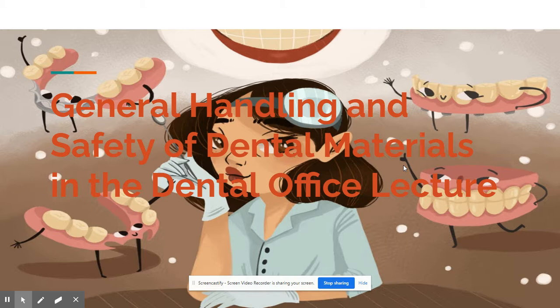Hazard Communication Program. OSHA has been enforcing a Hazard Communication Standard, HCS, since 1983. A chemical hazard communication program has 5 parts: the written program, the chemical inventory, the safety data sheet, labeling of containers, and the employee training.